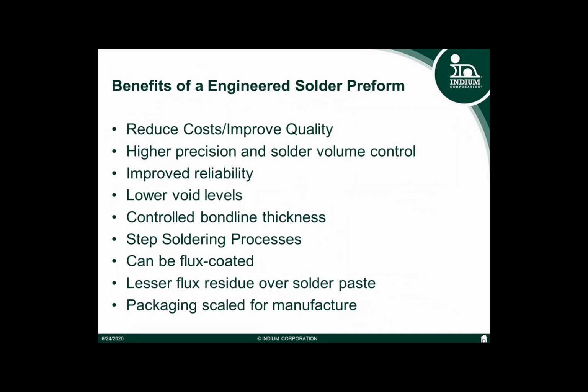But now, since 2006, the traditional SAC solders. And then further down, you could come again to tin lead at the lower melt point that you would traditionally have used before lead-free. And then beneath that, you can go all the way down to the tin bismuth alloys, and even lower to the indium tin alloys as well, that are around about 120 degrees Celsius.